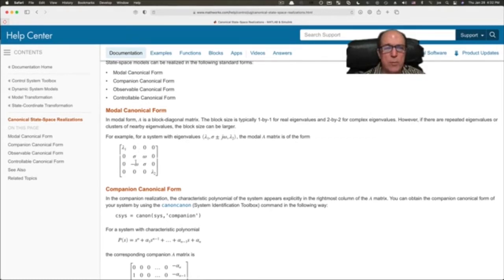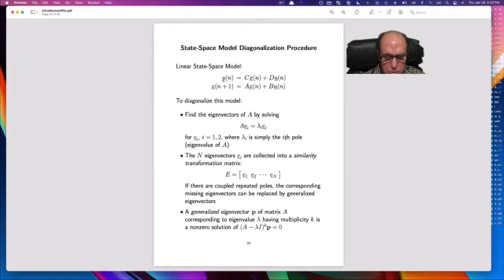There are a lot of different forms there. It depends whether you started with direct form 1, direct form 2, normalized, lattice. There are all these different forms. But whatever it is, it pulls out now as a separate subsystem. So you can now implement this as two parallel one-pole filters and a parallel biquad. And the B matrix and the C matrix will change as a function of how you choose this form in the biquad stage. But whatever it is, you just pluck it out and implement it separately. So that's usually what you really do.